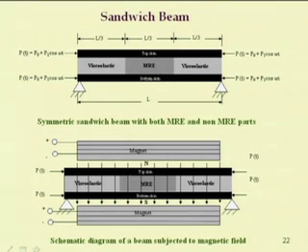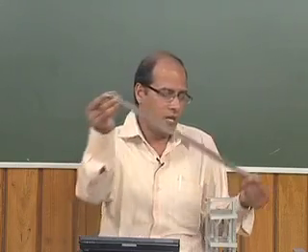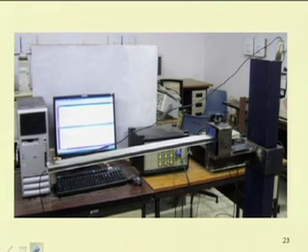In case of an MRE embedded beam, this is one MRE embedded beam. Here a magnetic field is applied to the system, and if you are applying axial load in addition to this, then the equation of motion of the system can be that of a parametrically excited system. So, you can study the nonlinear vibration of a sandwich beam under free vibration. Then its behavior may be that of a Duffing equation. You can consider this as a parametrically excited system when you apply force at the end, or you can have a base excitation. Then you can consider this as a nonlinear parametrically excited system. Also, in case of this nonlinear system, you may consider single frequency or multi frequency excitation.